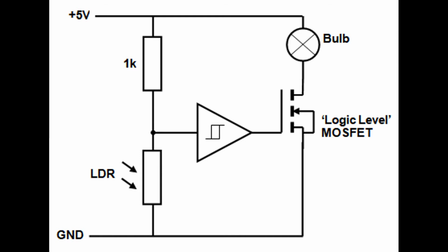To confuse matters more, the MOSFET used in this circuit is just a completely wrong MOSFET to use, but it is the only one I had to hand, so my results are not at all optimal. If you want to try this at home with a 5V power supply, you want to add a Schmitt trigger and a low threshold MOSFET suitable for 5V logic work. I will cover this in a separate video. In hindsight, maybe I should have just used a transistor and an LED, but that circuit is so common it was boring. I wanted to do something different.